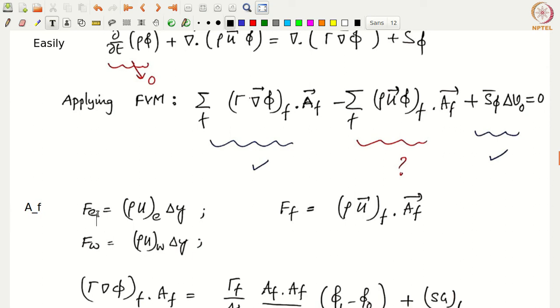Whereas now I would like to define our flow rate as rho u bar f dot A_f bar. This takes into account the plus minus automatically depending on the face we are at. Of course, A_f bar is now pointing out of the cell that we have focused on.